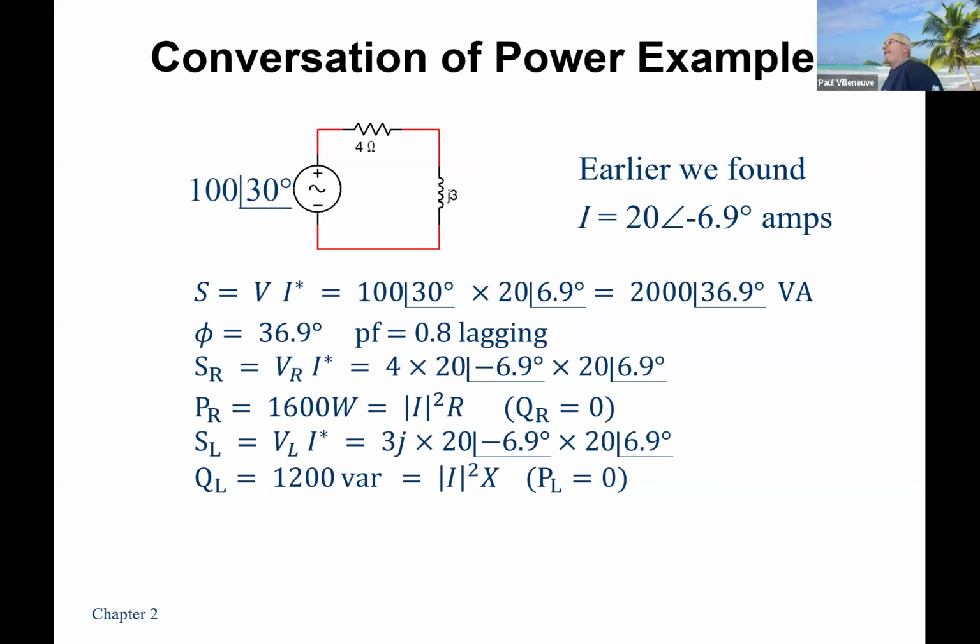Anything there? The voltage is positive. That almost tells the story. Is negative? If it's negative, then it's leading. You're both kind of saying that you're close. Alan? That's part of it, but the real reason is the voltage is here and the current is here. The current lags the voltage. So everybody was kind of saying they were close to saying the whole thing, but what I was looking for wasn't the fact that the angle was negative or that the voltage was positive. It was the fact that the current lagged the voltage, because doesn't that have a negative angle? And isn't that a negative angle? Still a lagging power factor, isn't it?